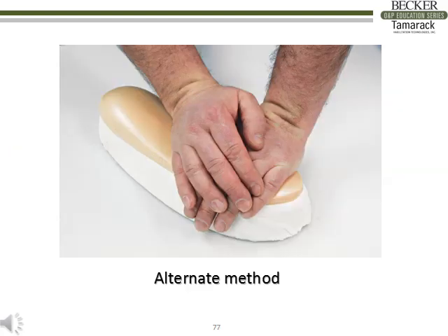Here is an alternative way to inlay when you do not have a vacuum press available. Heat the relief area of the mold or the soft insert and then press down evenly by hand. The result is nearly the same as if you used a vacuum press.